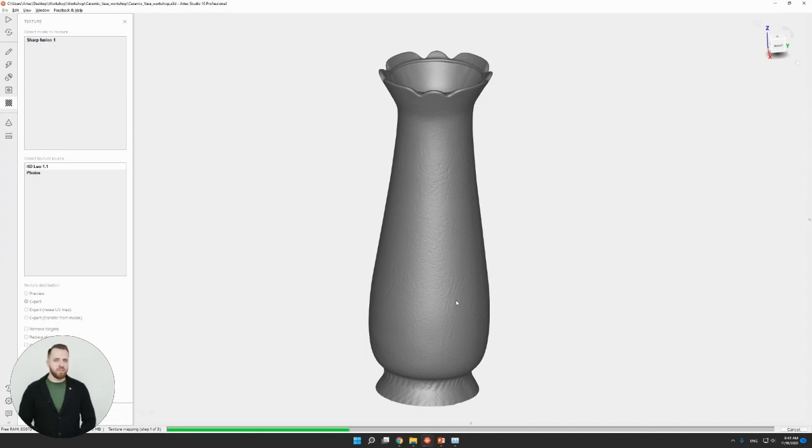There is a very interesting trick, which we'll talk about a bit later, but I'd like to mention that if you are dissatisfied with your texture, if you applied your pictures to your model and you can still see some blurry areas, or maybe you are dissatisfied with artifacts, you can always take some extra pics, and you can take them from a closer distance, and that way you can locally improve the quality of your final texture. We'll elaborate on that a bit later, but now I just want to let you know that if you're dissatisfied with the texture, there are different ways of fixing that.